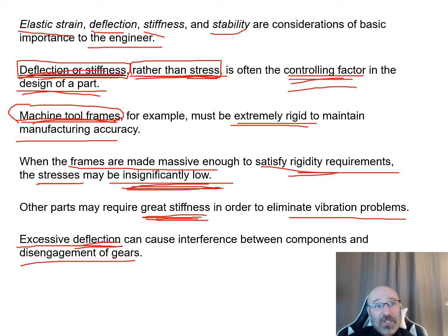So if we get the deflection right so that the system works together for this gear situation, then we know the deflection is going to be minimal and it's not going to interfere between these individual gears. We can go with that, continue on, and back out our stress values for those gears as well. This is thinking of things that we've seen in ME14 and some of our other classes, but applying them to a design criteria.